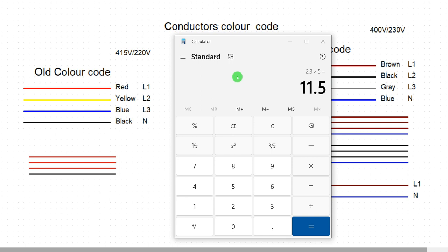If you are working with 230 volts and you are supplying a power circuit, you are supplying a power appliance or equipment, that is a power equipment, so the voltage drop within that your supply, within that your circuit should not go above 11.5 volts. Okay, all right. Now let's say we have this 230.